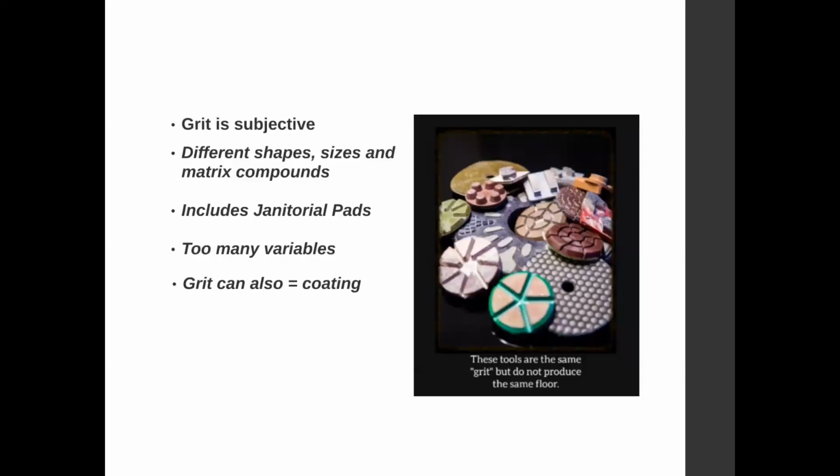One of the, I guess, maybe not for all specs, but still fairly common, you'll see some type of grit designation: finish to 400 grit, start at 80 grit, end at 1500 grit. And a lot of specifiers believe this language to be very objective, when actually saying 400 grit could mean literally thousands of different things. What type of material is the abrasive grain? Is it a universal size? Is it an average size? What is the matrix of the abrasive grain? Is it industrial diamond? Is it metal chaff?